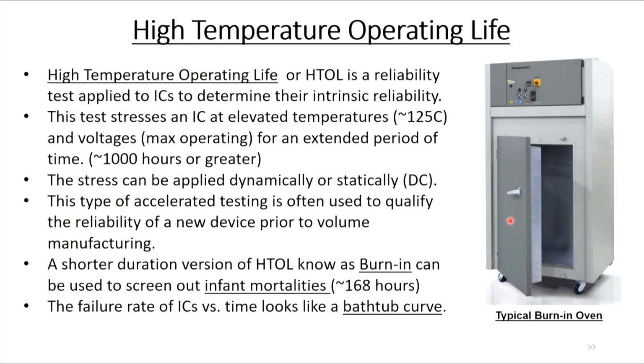Now, there's a shorter duration version of HTOL known as burn-in. And we use burn-in to screen out something called infant mortalities. And I think a typical burn-in time is only 168 hours, or is it different than that now? Okay. I show a typical burn-in oven off to the right here.